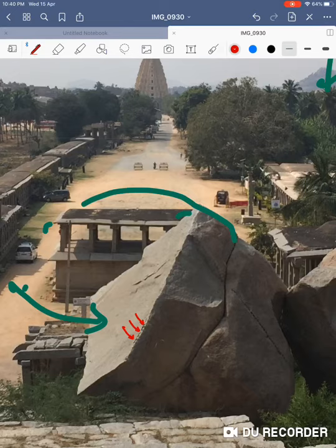I hope you are able to now recall the lecture that we had last time on stress concentration. So there would be a massive stress concentration here because of these grooves and the wooden blocks that were expanding, and that would cause a stress that would cause fracture in this entire material. The fracture would initiate here, and because it's a brittle material, the entire thing would just fracture all at once.